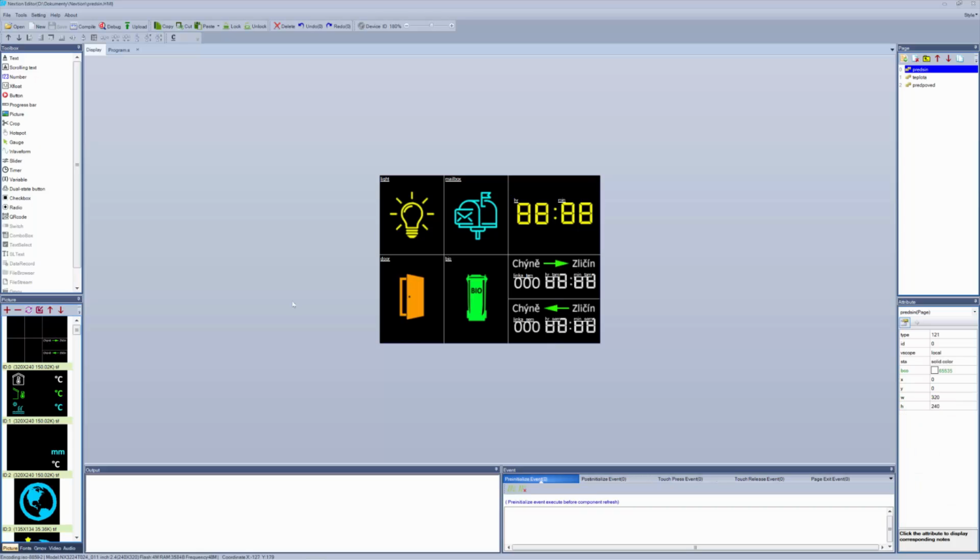The last piece of advice I'd like to give to you is you can change any object, any text or any picture into a button. When you select it, you just click in here, Send Component ID, and I will show you how we configure it in the ESP Home. Because even the cheapest display is touch sensitive, so when you click on this bulb, in this case, it will generate an event and send the component ID 2, and we will catch it from ESP Home, and we will create an event to turn off the lights in this case.